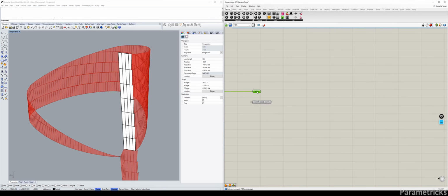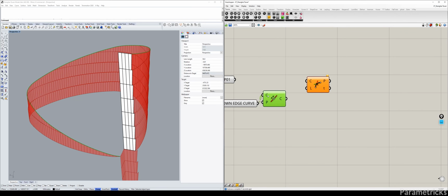All right. So we got a point, we got a line, and I think for this we can do a discontinuity because we know this curve is a polyline. Oh, I just found out we have yet to join our curve. So I'm going to quickly flatten that part so that we can have one single curve. It's still broken somewhere.